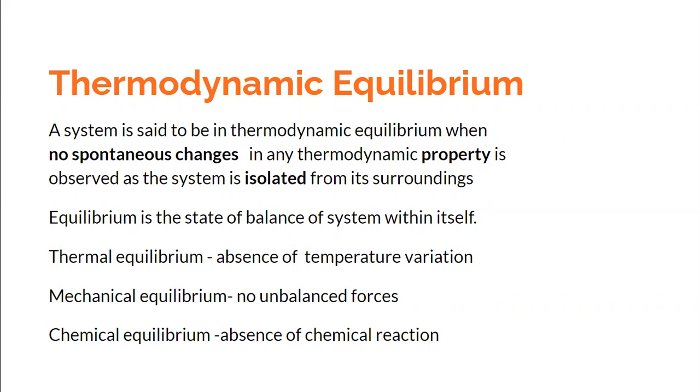We need to be clear that when you talk about any system, and when we were stating the state of that system having a certain thermodynamic property like pressure P1, volume V1, and temperature T1 at a given point of time, we were assuming that those properties like pressure, volume, and temperature would not change at that moment when we were specifying those properties. And why is that so? That is because that system was in thermodynamic equilibrium.